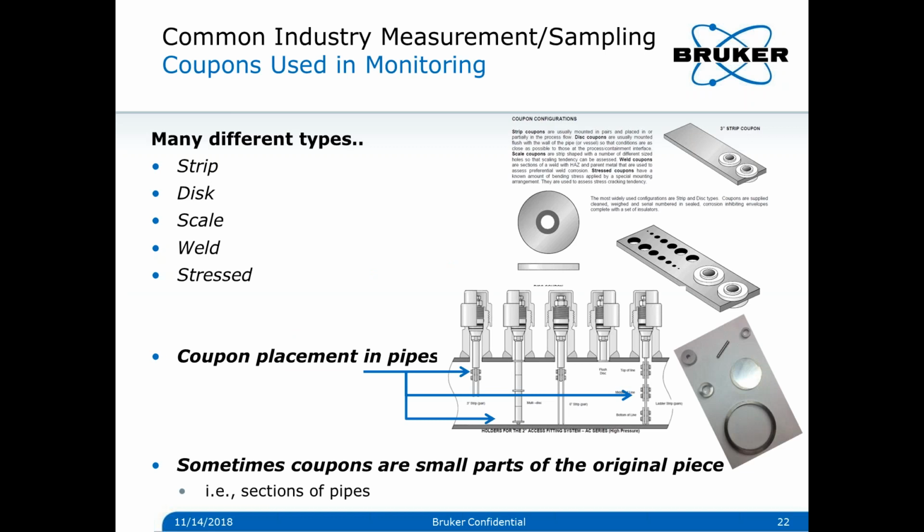To test corrosion, because it is a very complex process, most of the time it is better to use samples called coupons, which are placed in the same conditions as the pipe, either externally in corrosion chambers or standard corrosion protocols, or directly inside the pipe itself, and those coupons are then removed and measured in a regular manner to study how healthy the pipe is.